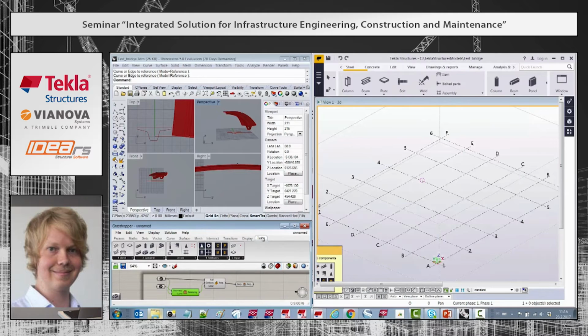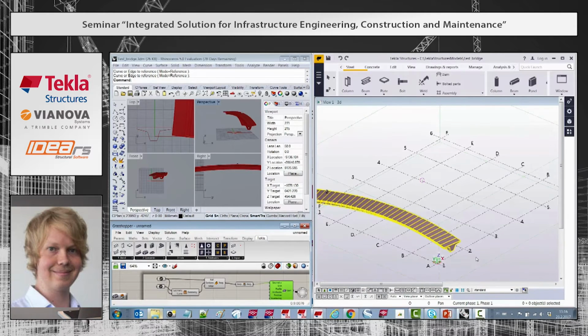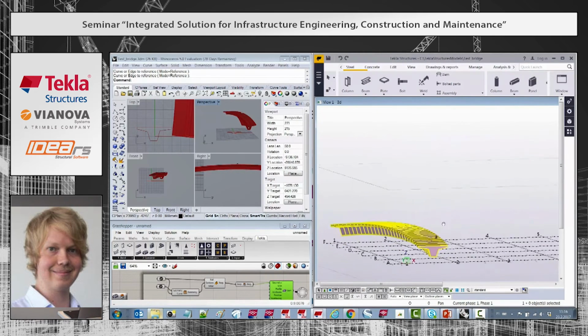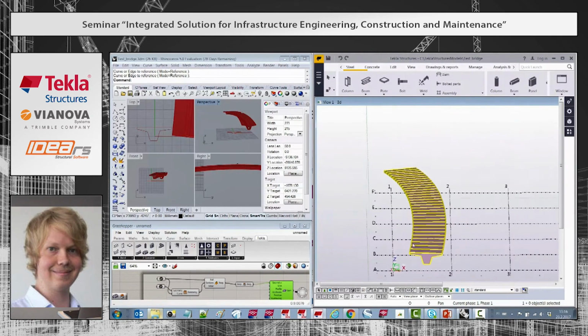let's add from the Tekla tab page this item component to Grasshopper, which creates the item in Tekla. And I will just wire it here. And as you can see, the solid item appeared in Tekla instantly.